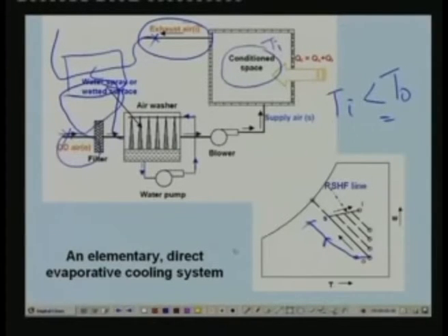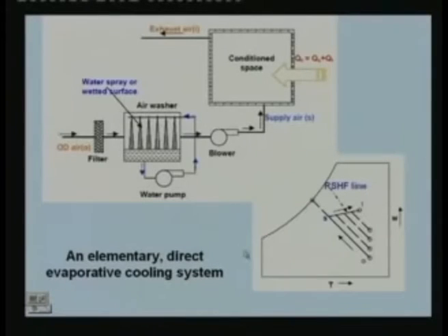Of course, achieving good heat exchanger effectiveness using an air to air kind of heat exchanger is very difficult, because you have to have a large surface area, etc. That means you have to use a compact heat exchanger if you want to have good effectiveness. So you have to see the benefit versus the cost involved. But in principle, this is a simple modification which can give a certain improvement.